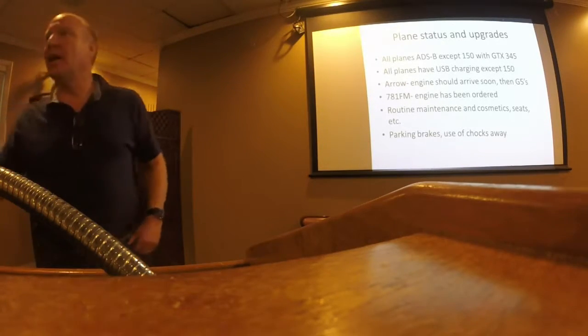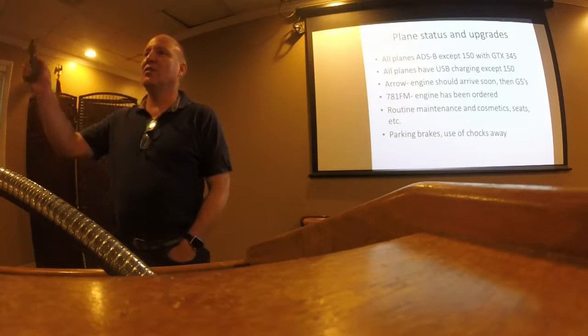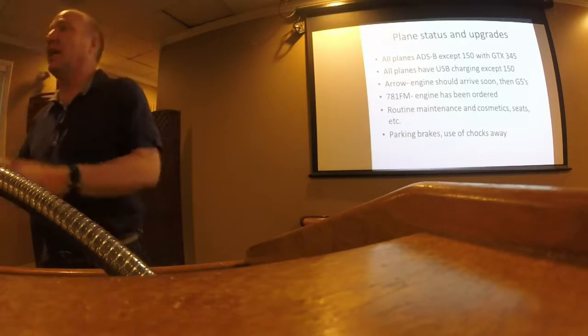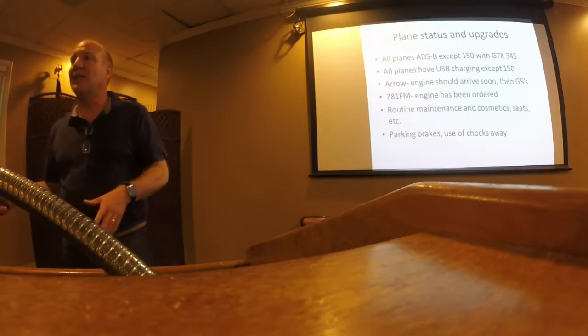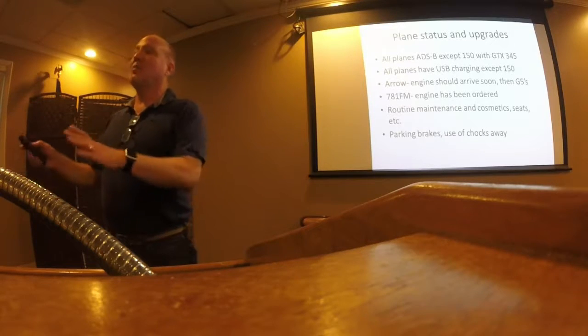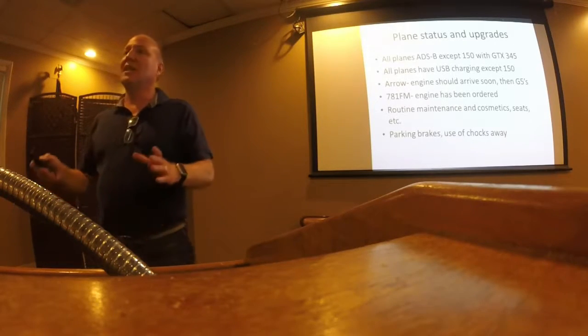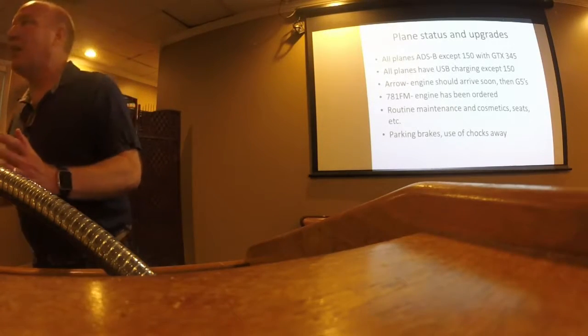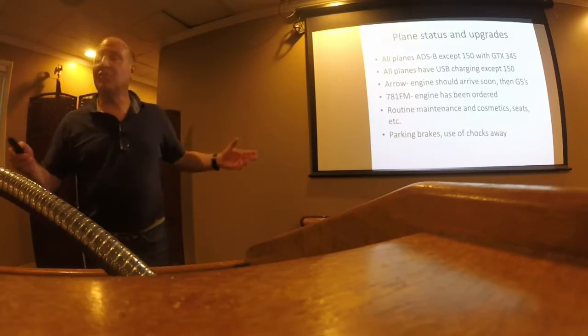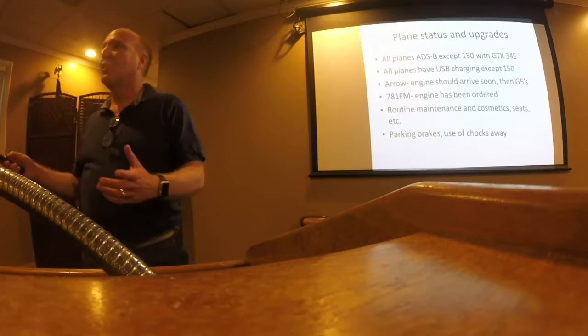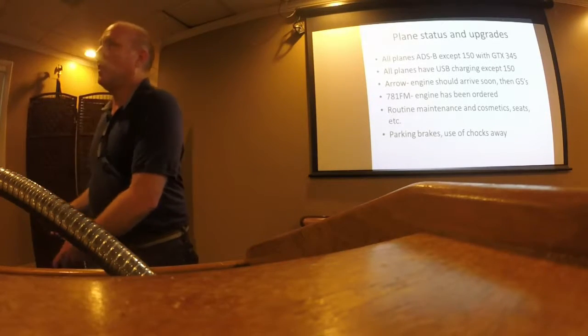If you're going away on a trip and you go somewhere busy, where they've got an FBO, jet traffic, and guys running around, and you're leaving the plane, they will not want you to have the parking brake set, because they may need to tow that plane out of the way so they can get a jet in. So take chocks with you. If you're going away from Tipton, feel free to take the wooden chocks.